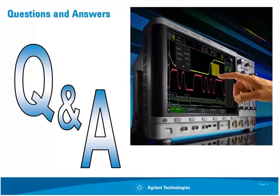And a last question, are there any disadvantages of fast waveform update rates? In my opinion, there are no disadvantages. However, we have had some input from our customers. One phenomenon that you will see on a scope that has an extremely fast update rate is that some customers say your waveforms look fuzzier, they look more noisy, and they think our scopes have more noise. What the fast waveform update rate is actually doing is capturing more noise.